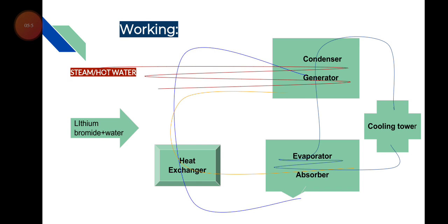One of the most important things to note is that the temperature of the cooling water is enough to cause the hot water vapor to condense into liquid as it comes into contact with the surface. So then this process repeats again and again, and the chilled water tube then runs into the evaporator, bringing all the unwanted heat from the buildings, which was collected from the AHUs, diffusers and the fans. So that is the working of the vapor absorption chiller.